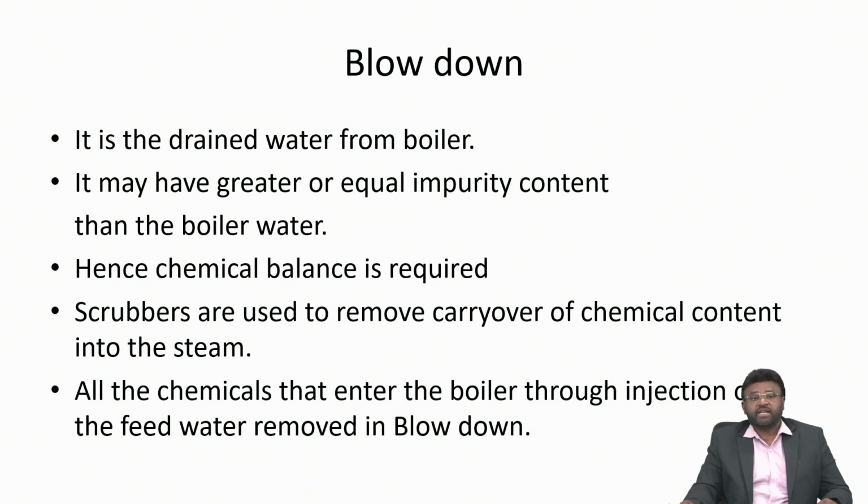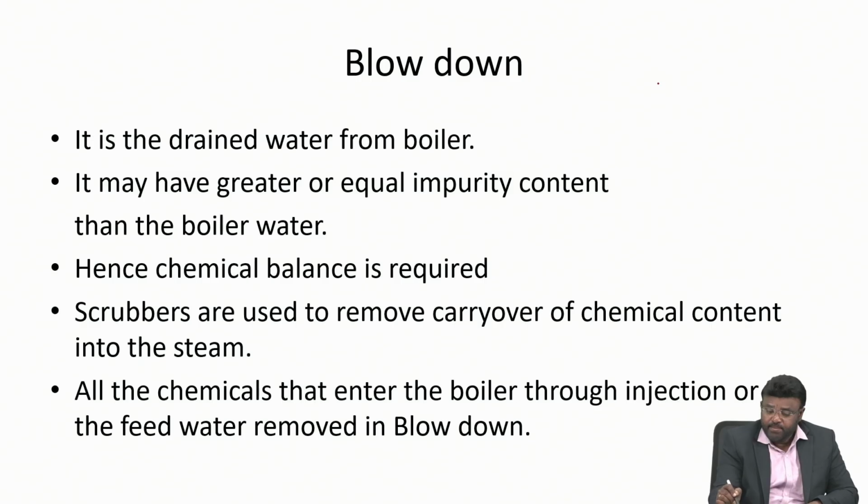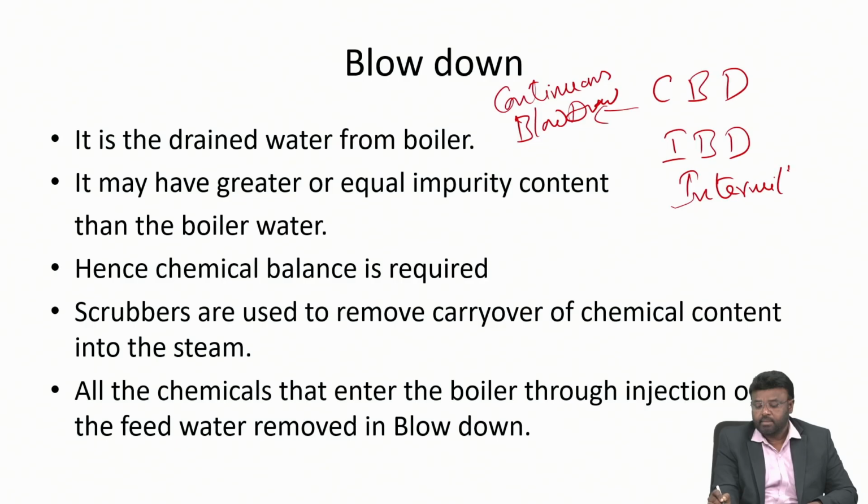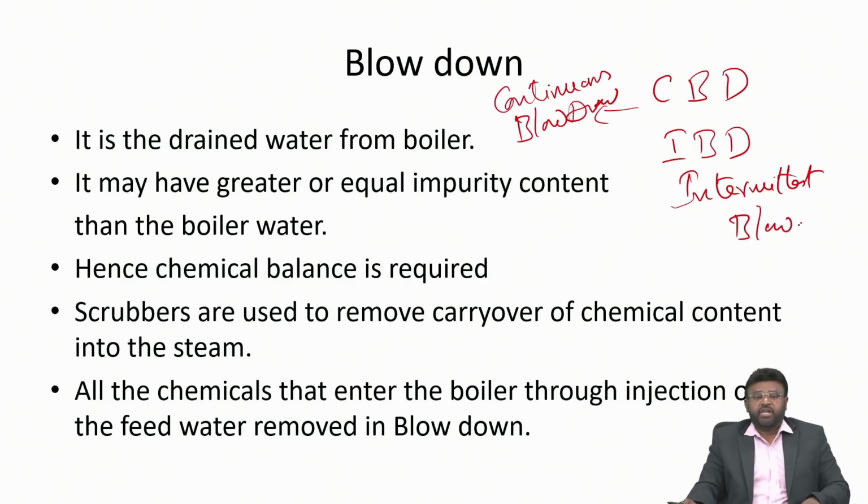Here there are 2 kinds of blowdown: one is the CBD and another one is the IBD. CBD is continuous blowdown, and the other is intermittent blowdown.